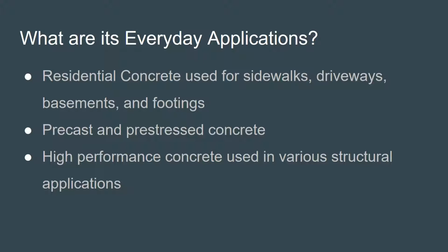Precast and pre-stressed concrete can utilize the benefits of increased early strength when steel slag is incorporated into the cement. Heat curing is often used for the production of precast and pre-stressed concrete, as steel slag responds well to heat curing and produces higher strengths than traditional Portland cement concrete. Slag cement in high-performance concrete has an increased compressive and flexural strength, lower permeability and heat generation, and a greater resistance to alkali silica and sulfate attacks.